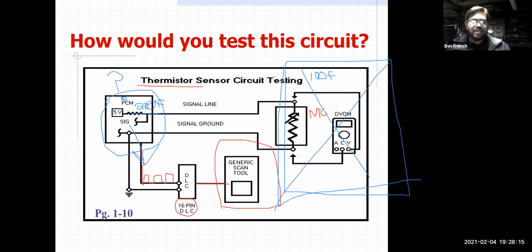Well, I've disconnected sensors, and you think, okay, well, the sensor's not there. The computer should think that now the coolant's like 30 degrees below zero. But you know what it shows me on my scan tool? 200 degrees Fahrenheit, because the scan tool data is interpreted data. It's not real. It's ones and zeros, right? It's what the computer thinks is going on that it's sent to your tool, and then your tool has to then redisplay it, right? So it's interpreted data.